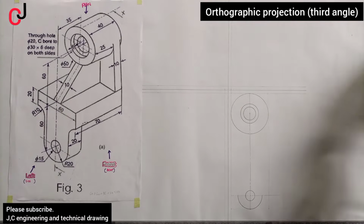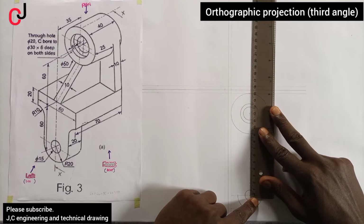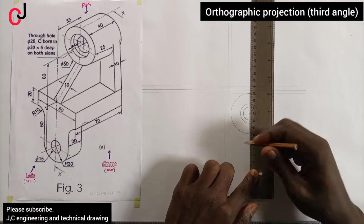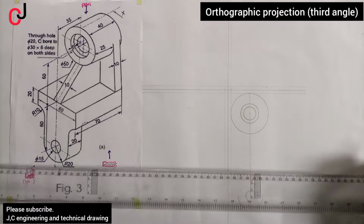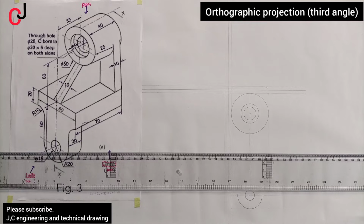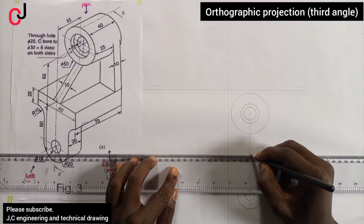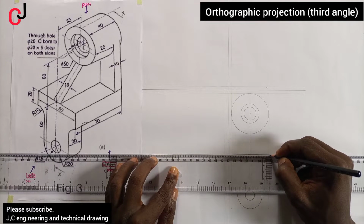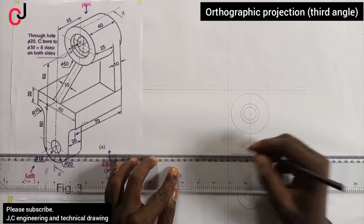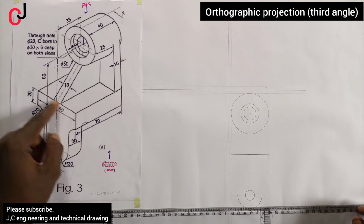So we'll measure 60 millimeter with our rule from the midpoint, from this point. 60 millimeter, we indicate it with a point, and then we'll draw an outline touching the two horizontal sides of our image from our side view. You can see, then, which is this.